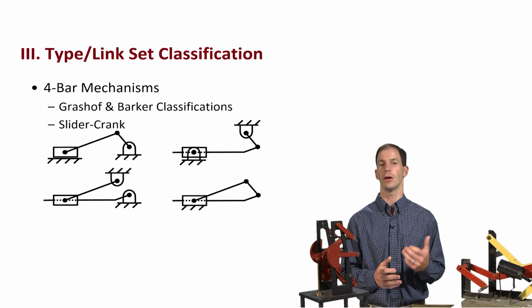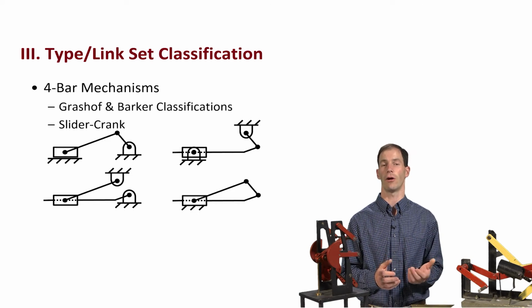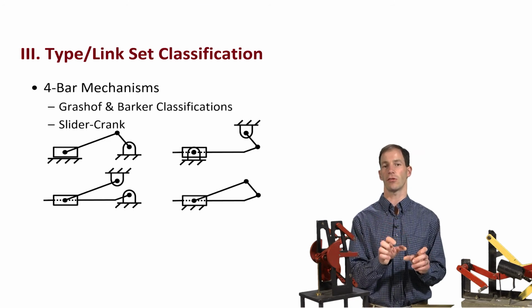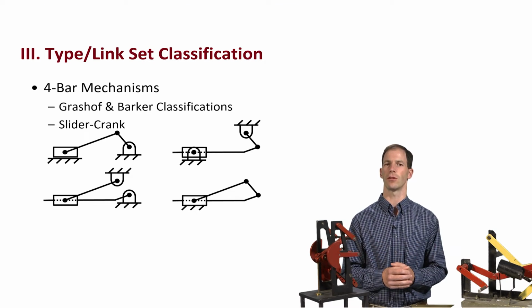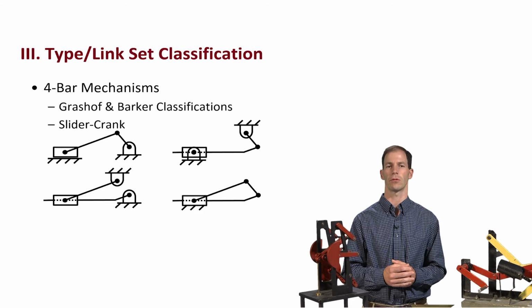So it does not have to be that the slider is moving on ground. The slider can be in space. The slider can be having a pivot on its center and be rotating about its center point in the turning block mechanism. Lots of inversions that we can look at and create some very interesting mechanisms.